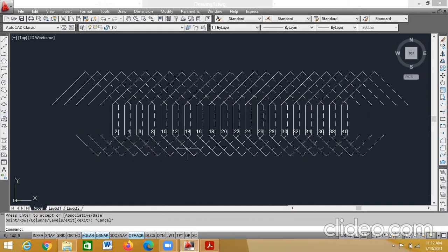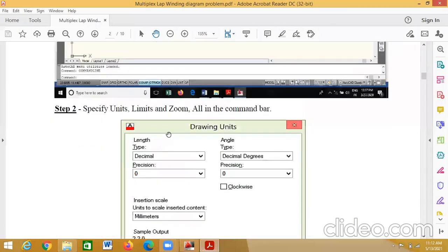So we have done all the, that is how many conductors? 40 conductors. All the YB/YF connections we have done. We have to number the remaining conductors at the top and the bottom by seeing both the winding tables. Here we have degree of reentrancy is 2, so 2 winding tables are there. Observe both the winding tables and mark the numbers of the conductors. Okay. So till here we have done. We'll do the number.